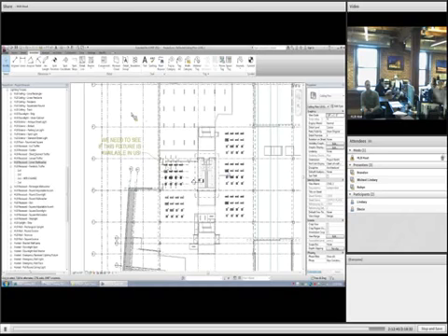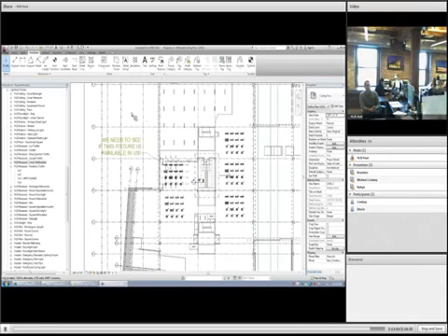Yeah, that's actually coming in through this little add-in feature. Revit MEP uses spaces rather than rooms. Rooms are three-dimensional, but spaces are three-dimensional plus they carry a lot of added data, more so for the mechanical side of things: heating and cooling loads, the number of people that will be in there, the use type.